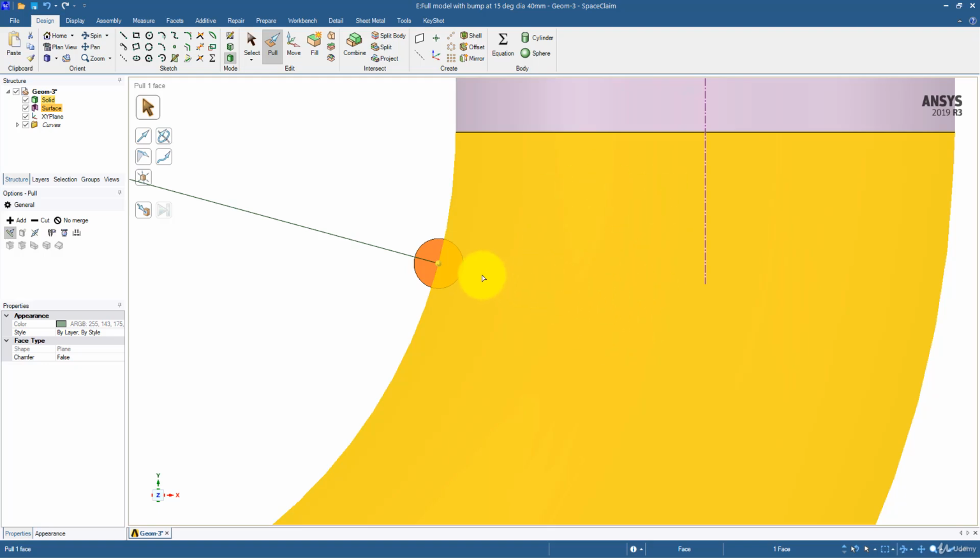So this will be gone because when we combine them, the remaining part will be the mixing elbow, and the only extra thing you will get is the outer part of the half hemisphere outside this mixing elbow. But if you use the cut command, this will cut the geometry from inside and then this will be deleted. And if you say no merge, this will make the geometry of this full sphere and keep the geometry intact without making any intersection or interaction with the main geometry. So I would suggest that you should use the cut command.